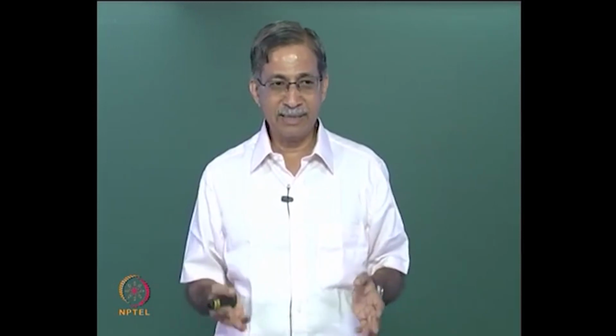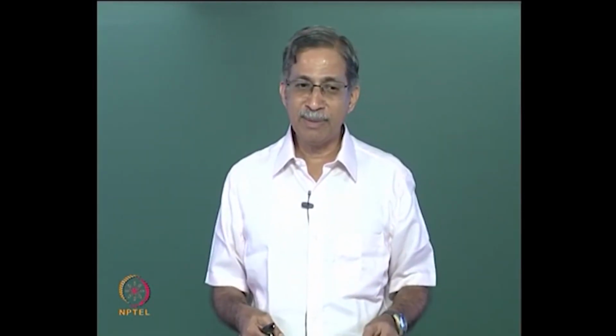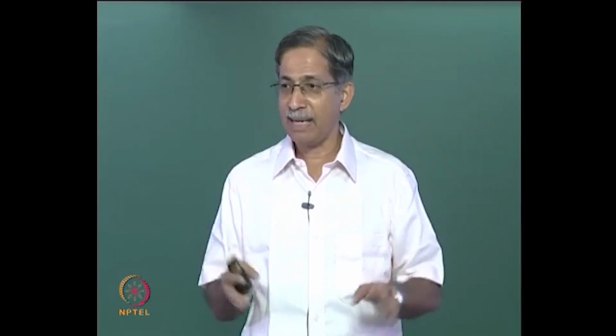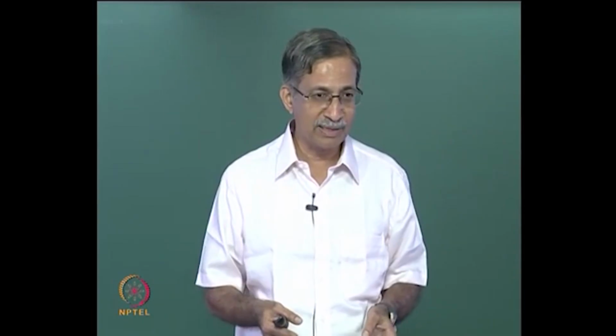It is a numerical way of solving simultaneous equations. If you notice, the superiority of the moment distribution method over the slope deflection method is that we do not calculate theta b and theta c at all, we directly get the moments, whereas in the slope deflection method you calculate theta b, theta c, and you plug those values back into the slope deflection equation. So here there are many ways to do it.